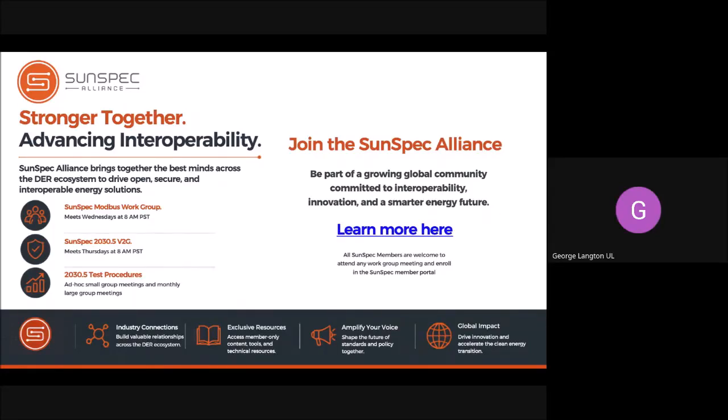That's where dynamic droop is your first evolutionary step. Then dynamic isochronous mode is the next one for inverters, because they're going to work that way. Don't even think about paralleling with generators, because again, the communications loop is essential. They will not see each other at all.